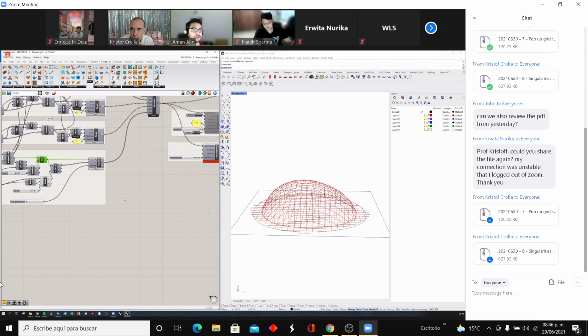And I can still have additional constraints which can guide the way these curves will behave. For example, all the grid points, if I see it in plan, can remain in the same line as they are in the initial grid. It just moves in z. So each point I can give a goal where it will just move in the z axis and not in the x and y axis. And it can still maintain the lengths. It can also still maintain the spring and every other thing. So what I'm trying to get at is, if you have a shape which is slightly deviated from this one, derived from Kangaroo, and because we are going to be flattening it out into a grid, that means technically we can make any shape. Because ultimately we are going to flatten it out and make it out of bamboo, right?